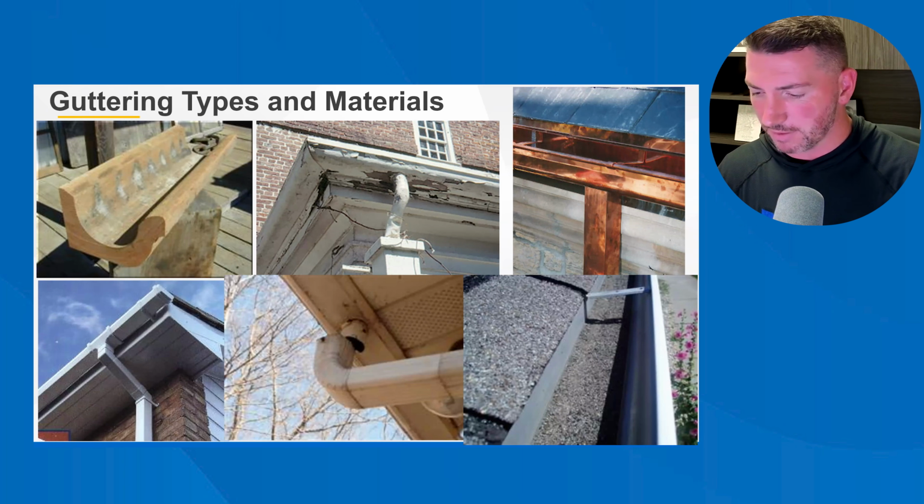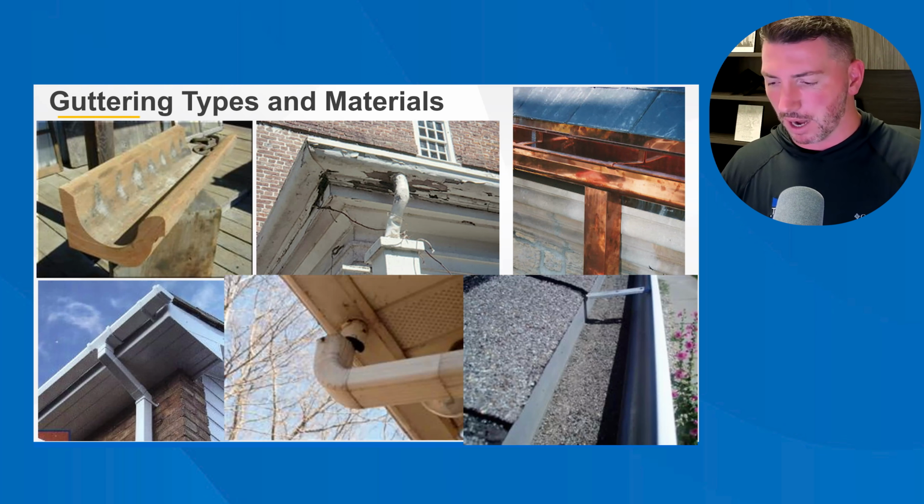The most common method of connecting the components is using aluminum pop rivets, and in a lot of cases, just self-tapping coated screws. Those very frequently fail, either from impact damage or building movement.